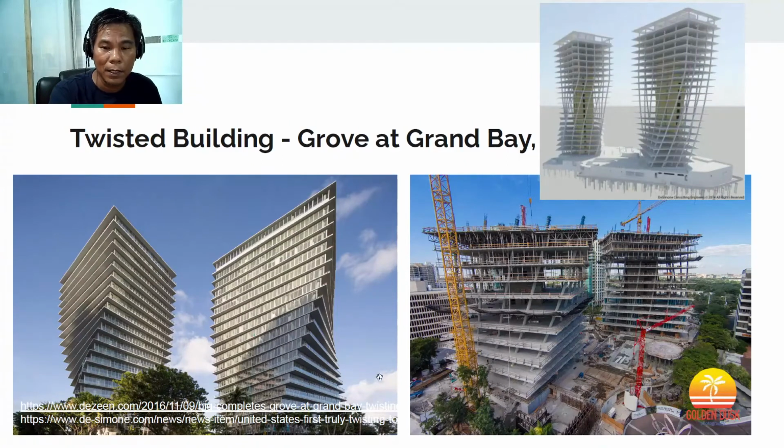This is a residential building, I think, and the concept is that the core of the building at the middle, which houses the elevator, is used to carry the building, the gravity load and the lateral load. As you can see, the columns in the outer portion of the building is actually in tension, not in compression. So this is quite an innovative structural engineering concept.